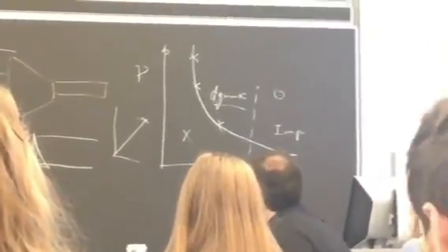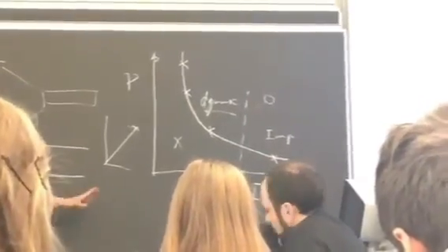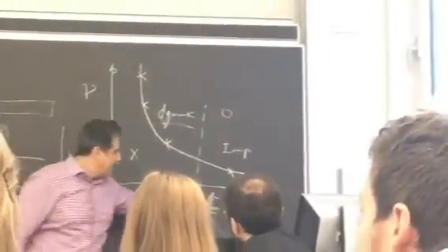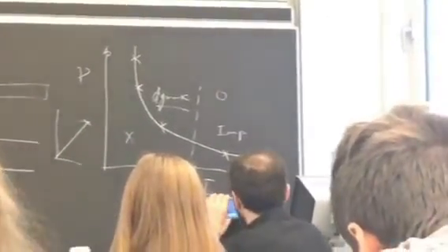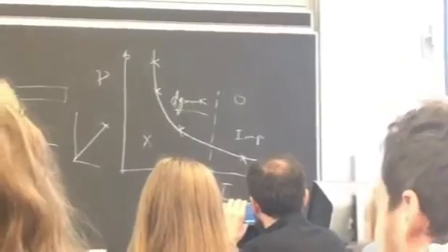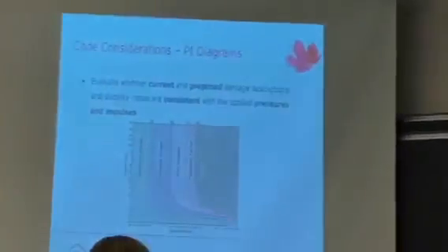Right? So essentially, if I give low impulse, high pressure, high impulse, low pressure, whatever combination, as long as I land on that curve, I have exactly the same damage. Of course, what does that mean? It means that the item has deflected exactly the same amount. Okay? So you see it here, pressure, impulse.